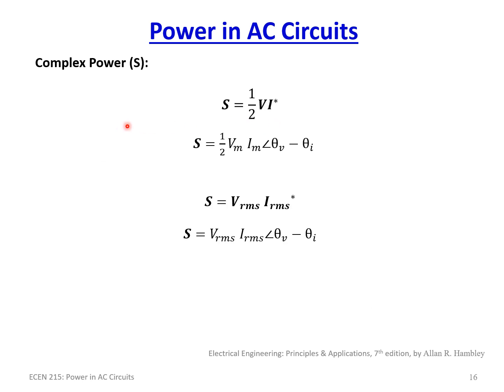So here's just some simple, straightforward equations. If you've got V and I straight out as phasors, then you take 1/2 V times I conjugate, which is 1/2 Vm times Im, the two magnitudes multiplied together divided by 2, and just the phase difference. And that will get you the complex power.